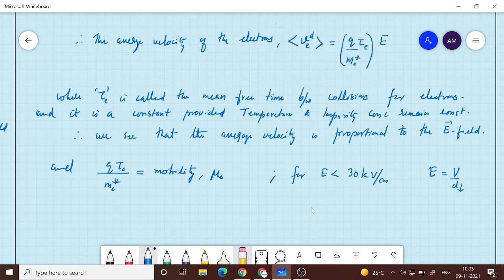And how do we create such a small region across which the potential is dropped? There are various mechanisms, like doping to a very high level. Most Zener diodes are very heavily doped with impurities. So that D, the distance between the p-type and the n-type material, or the depletion region width, becomes very, very small.